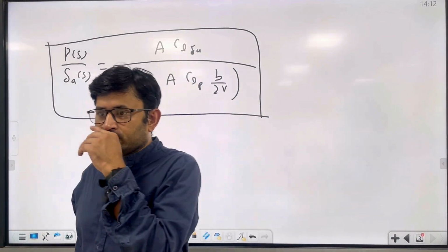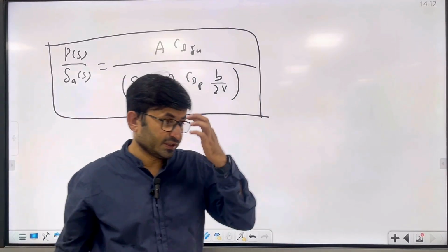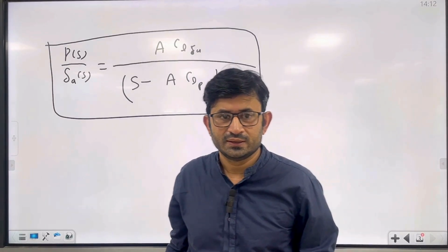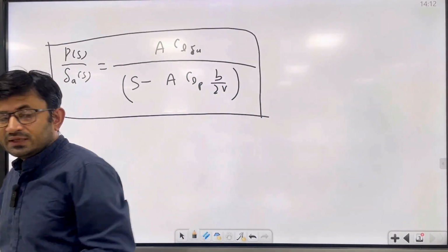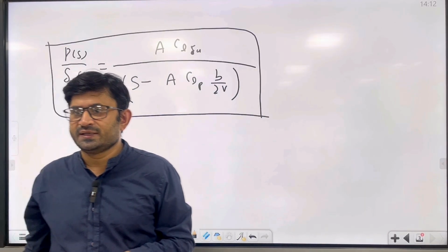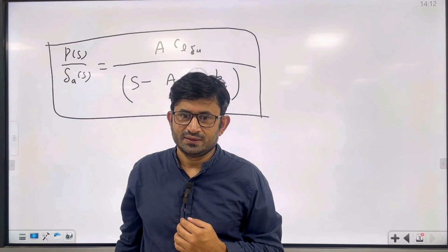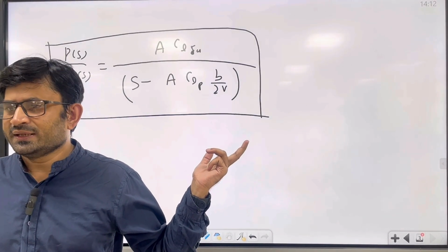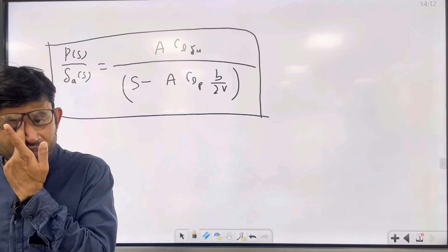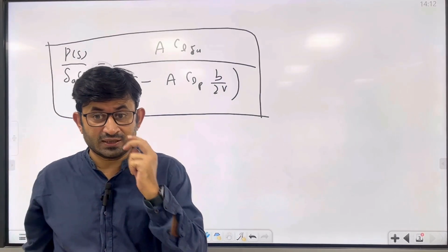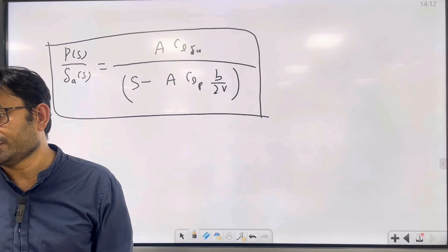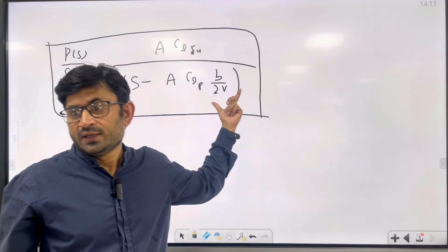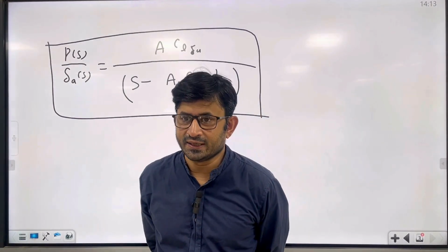Now, if you go back to my flight control and stability lecture, you can find out how we found the Clp value and the Cl delta A value. Now, will there be any kind of oscillation? Can anybody tell? Is this a first order or second order system? There is no square term here, so this is not an s squared system. So you will not get any kind of oscillation. And this pole, is it negative or positive? Just see, negative, right?